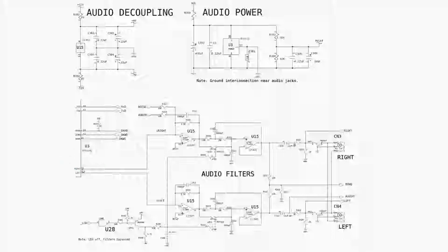We'll just talk through the right channel here and assume that's the bad one. If that audio signal is making it to the PCB trace, and this op amp is bad, well, that would obviously cause us an issue. If the solder joint to this pin was cold and the audio signal was getting up the PCB trace but not into the chip, again, it would block the audio chain. So I'm really kind of following the audio through the audio chain. Assuming the audio is getting in and the AV ref voltage is correct here, I should get audio out that's swinging above and below the system ground reference.